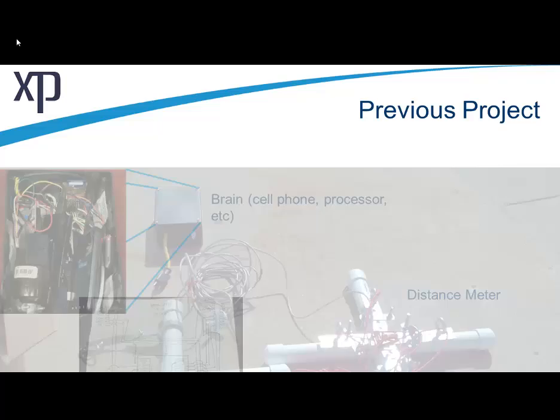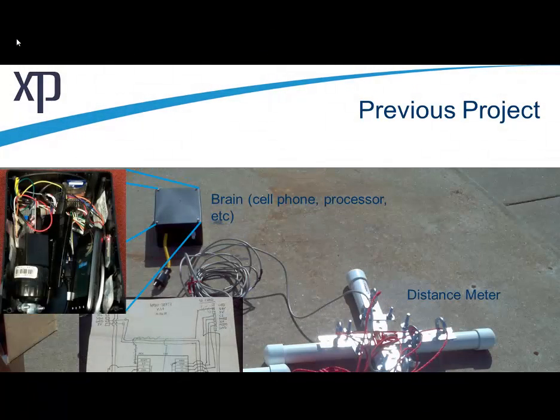In this particular project, we had a certain lift station that had a level indicator that was not functioning, and the mag meters on the pumps themselves were also not to be trusted. So unfortunately, there was not money to install a meter there, but we could actually install a depth sensor, which we did. This is some of the implementation.